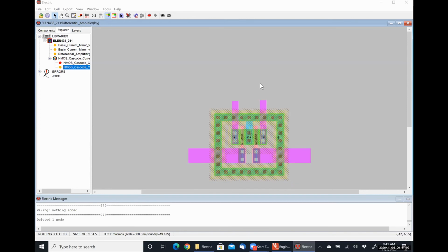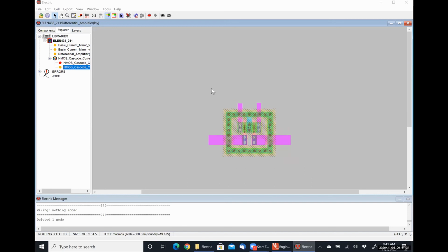I see the connections. It's just kind of in the middle of the block. It's kind of weird looking, but you can definitely see that. What I'm saying is there's a way to actually see the layout so that we can run our wires strategically and make them wider, because we're going to have longer runs. At some point we're going to have to think about effectively doing a large power and ground bus.